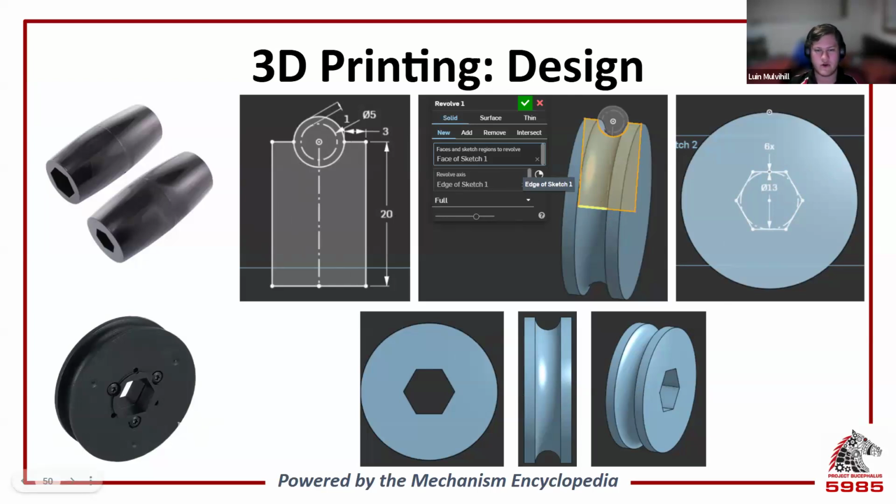So with our bore, we don't need to worry about using the 3D printed inserts because Polycord is unable to transfer high enough torques anyway. You can also make pulleys for 2 or more polycords, so you just add another profile next to it, so you can power multiple things off of one axle.